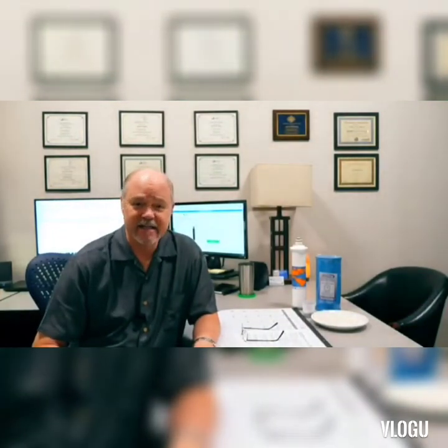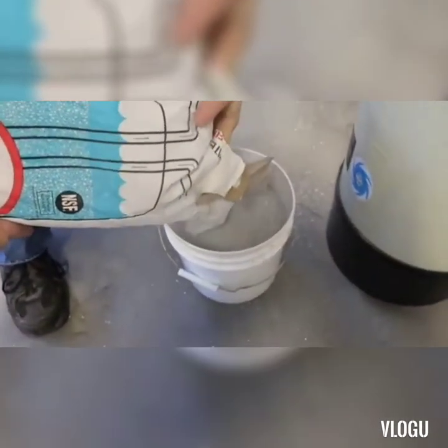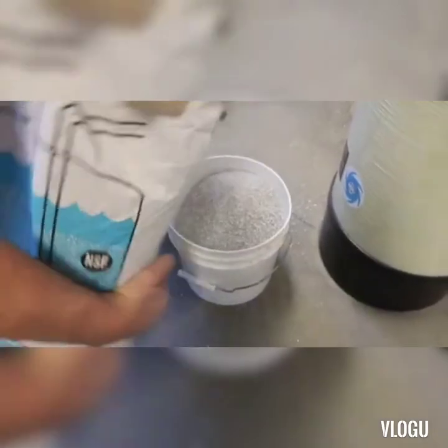There's a number of ways that we attack acidic water. The most common is using a material called calcite and flow water through that calcite to raise pH. Calcite is a mineral that's very high in alkalinity. In fact, it's made of a lot of calcium, and calcium is very rich in alkalinity.